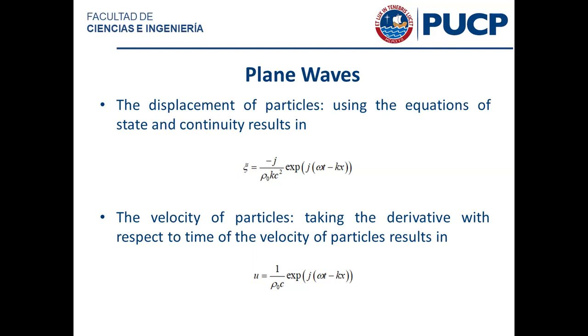So there is a factor of -1 in there, in the specific acoustic impedance when you are dealing with a plane wave traveling to the left rather than to the right. Okay, just be mindful of that because that's going to be important eventually, in some other portions of this theoretical discussion of acoustic waves.